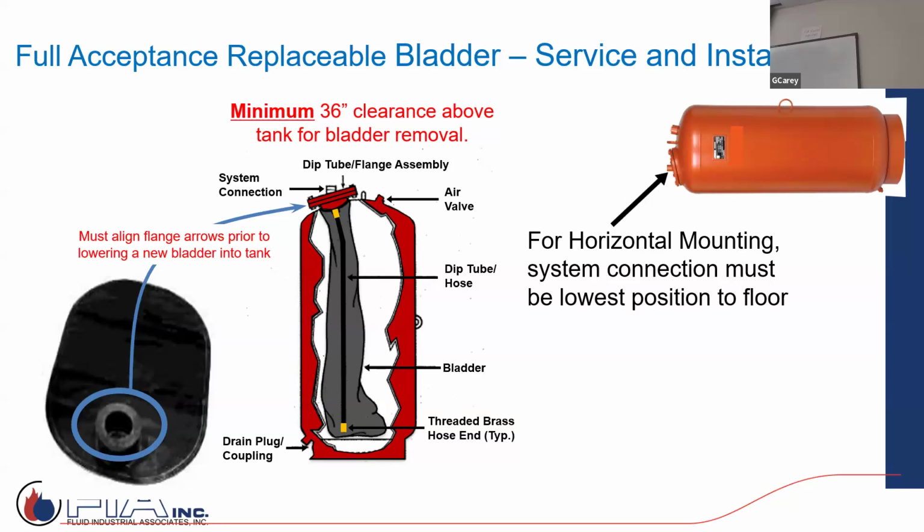We had a situation downstairs years ago. We had a couple of boilers that we had operating for heating as well as we used it for a little bit of educational. The sticker from the boiler manufacturer said, I think it said up to 50 pounds. So the boiler was rated up to 50, but we were only using it as a 30 pound. It had a 30-pound relief valve, but the sticker said 50. And the inspector caught us and he was like a stickler.